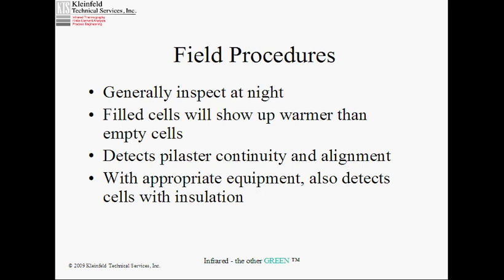The empty blocks, the empty cells in the blocks, respond differently than the filled, and this is both a thermal conductivity and a thermal mass issue. Generally inspected at night, the filled cells show up warmer because they're holding the heat essentially, and you can detect both the continuity of the pilaster and the alignment of the pilaster.